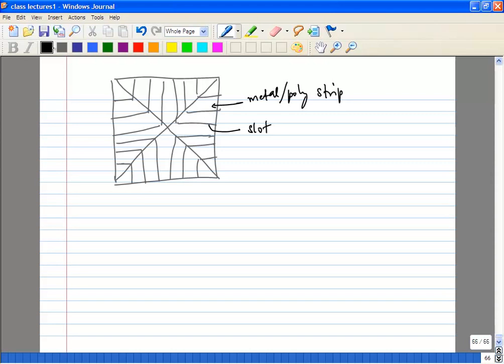Is that clear to everyone? So eddy current tends to flow in a particular direction, circular, and now you have completely stopped the flow of that. And you want to ground all of these strips because that gives the best shield. So to connect all the conductors together, you would typically put, let's say, a central line, a diagonal line to ground them effectively.